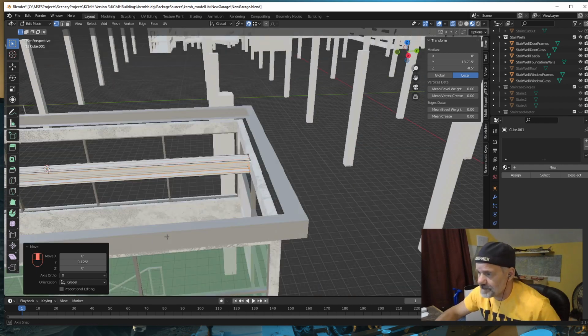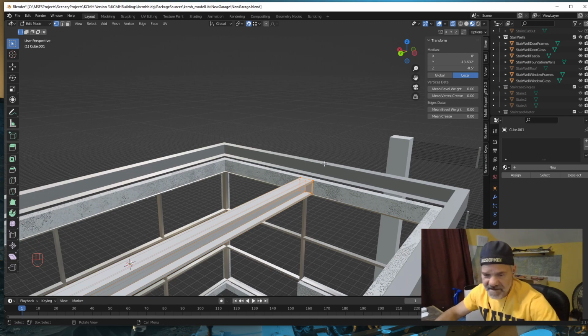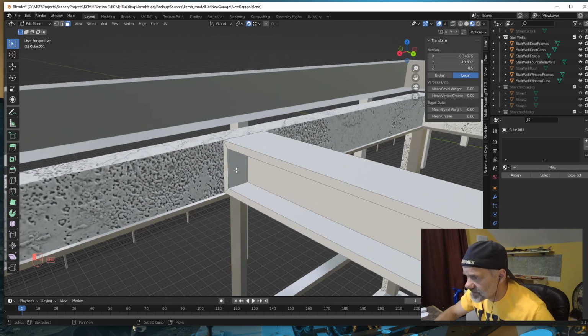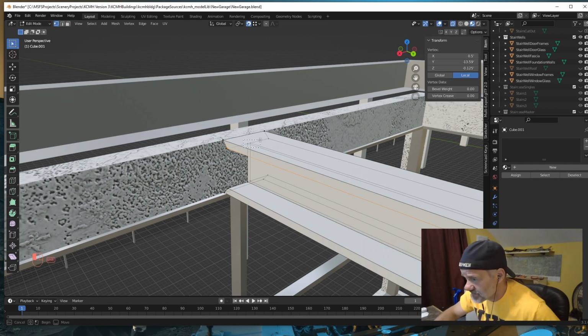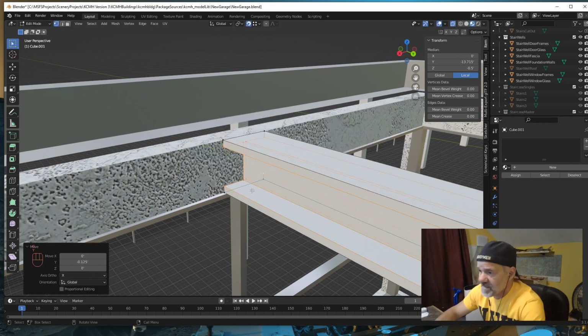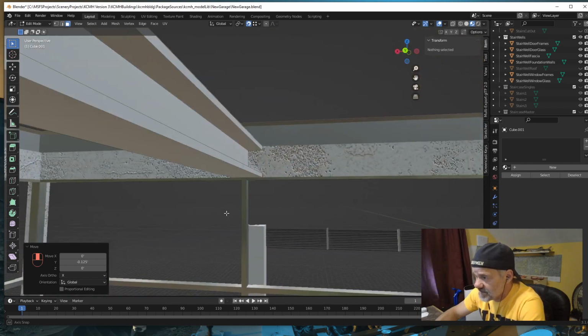Now we need to do the other side. All right, same thing. Let's select these and hit I so we focus in on that area. Face select, turn off ghost. I didn't have to, but it's a little easier in this particular case. Select those, delete faces, select that face, delete that face, and then vertices select, ghost, and select these vertices that I want to move. And move those to this Y. And there we have our I-beam. See how that is? Okay.